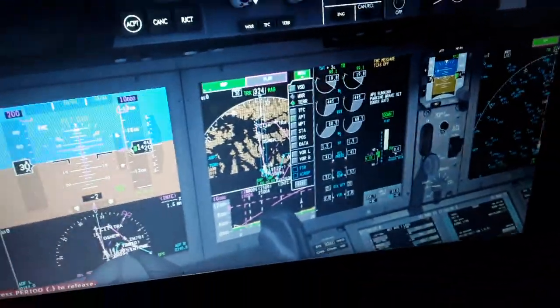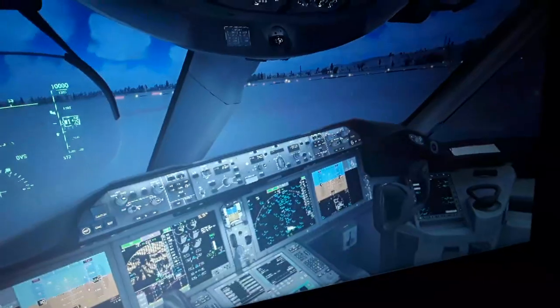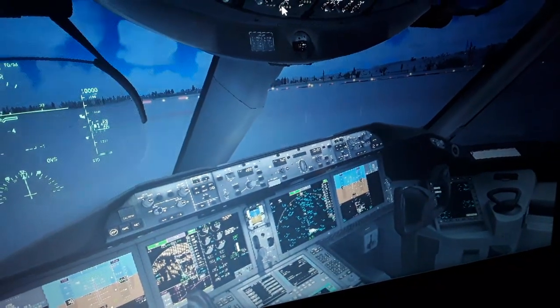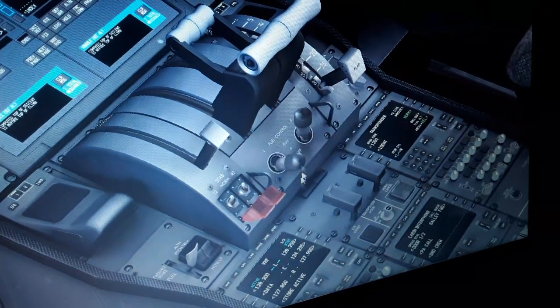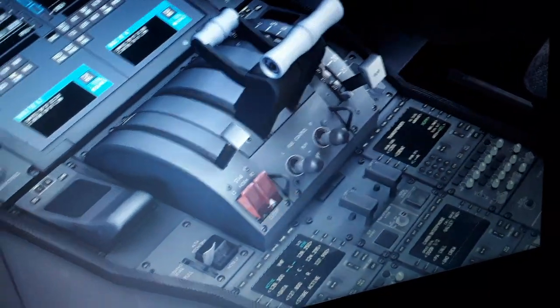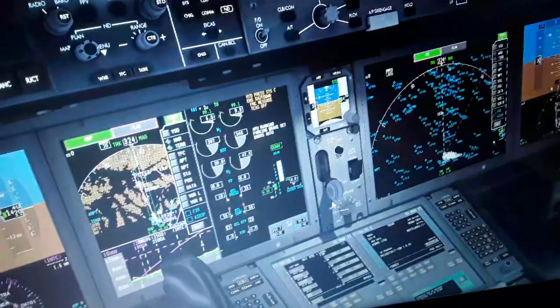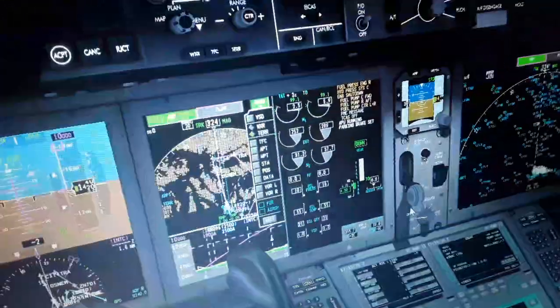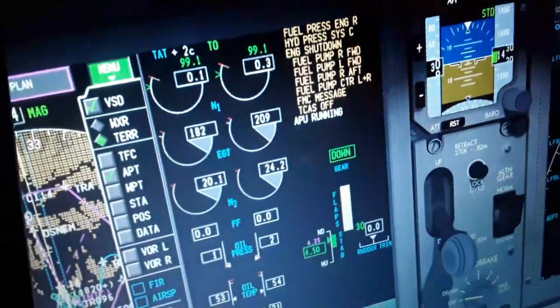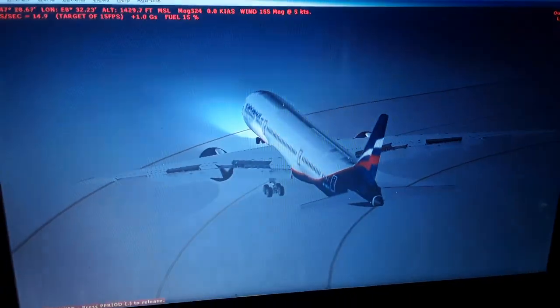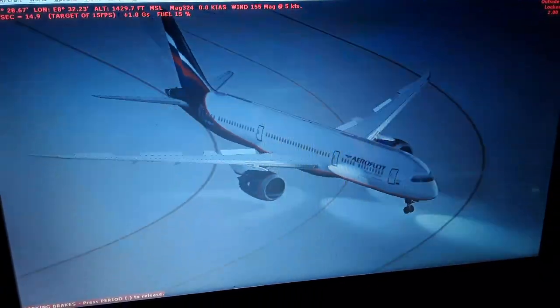Back to the engine start. So we turn off both engines. We use some lights over here, landing and nozzle steering lights. So we turn off both engines here. Fuel control to the off position. So you see the messages, the pumps are off, the engines are going off right now. So we need to restart them. Close the engines.